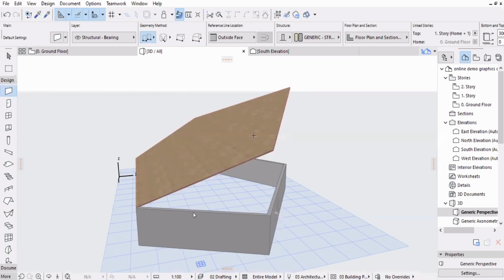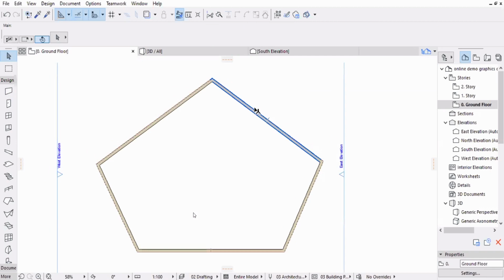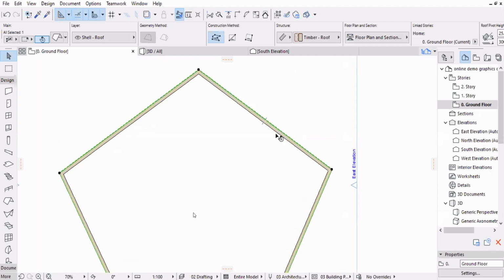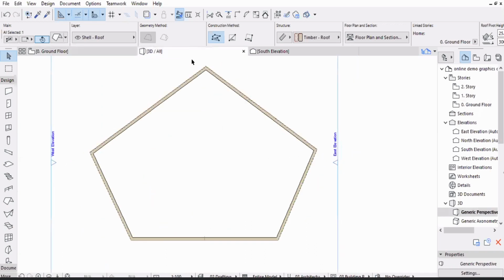What I'm saying is, for this roof edge to cut these walls, which are extending above the roof surface, the overhang has to be a little bit more than this edge. The roof cannot be on the same edge as the walls and cut the walls. It will never happen. It will always have to be slightly more. Okay, I'll explain this.